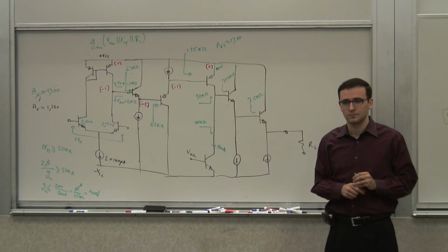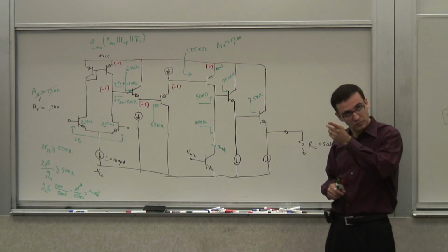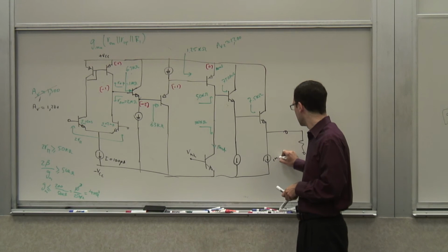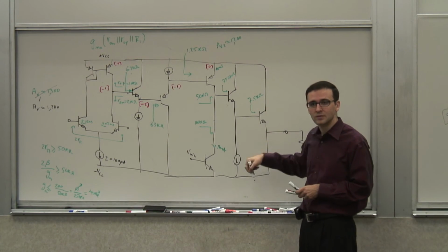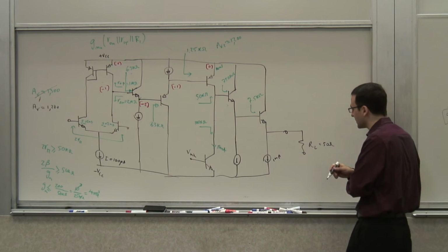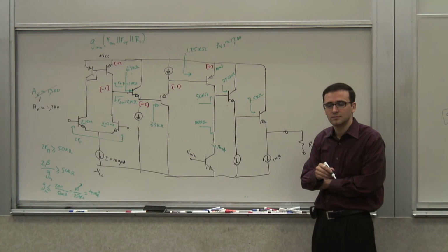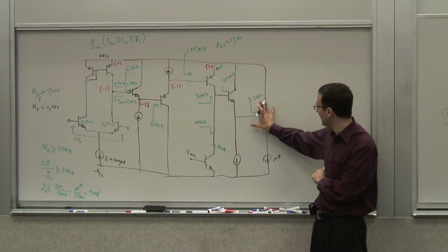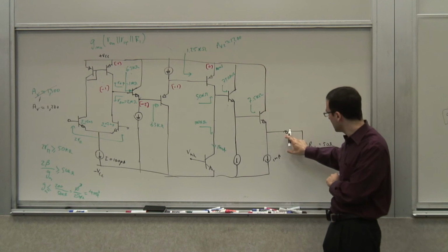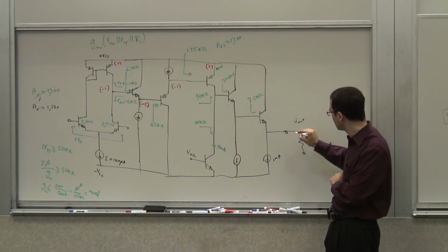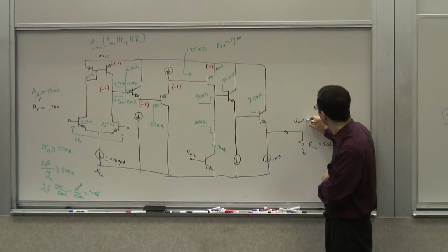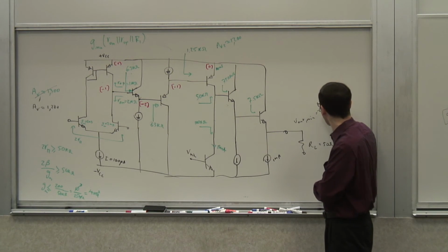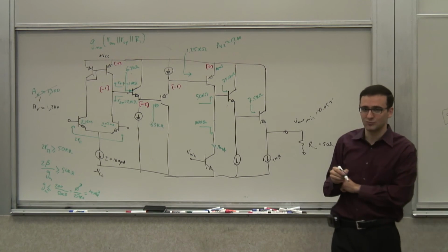Isn't the minimum output voltage limited by the current source driving? So that's one thing. So you said, well, I just kind of implicitly say this is 1 milliamp, right? Because I said this is 25 ohms Rm. So if this were running at 1 milliamp, how low can this voltage go? What is the lowest? Well, the lowest is when this guy is completely off, right? It can't source any current. So even if this guy were not there, what is the lowest voltage this output V out can be? Minus 0.05 volts.